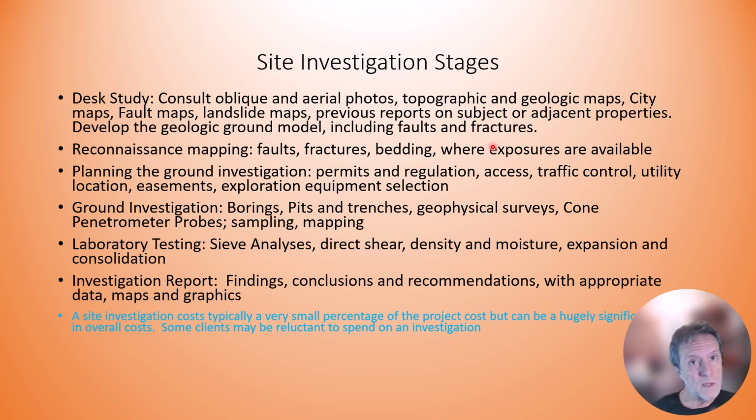Look at access. Can we get a drill rig in there? Can we get a backhoe in there? Do we have to demolish something? Do we have to open gates? We got to look at if we're drilling on or near roadways. We've got to get traffic control plans, permissions from city for right-of-way access. Very importantly, very significantly, we need to know where any underground utilities are. Water lines, storm drains, electric, gas pipes, etc.